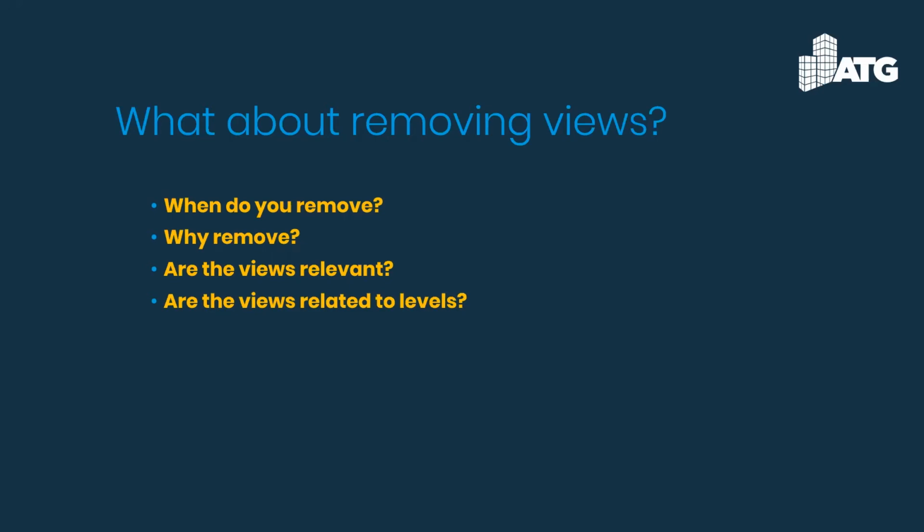If there are any camera views that you want to retain, what I tell people is go in and give it a name that is relevant to the project, relevant to what you are looking at, so it does not get removed. If we see 3D view 1, 2, 3 up to 90, that means you have way too many camera views. That is going to make the file size that much larger.